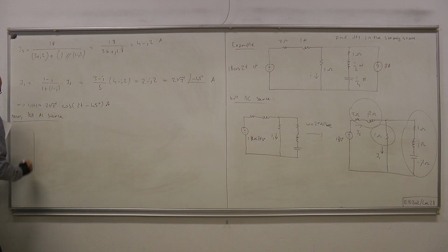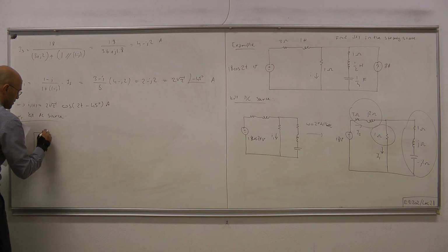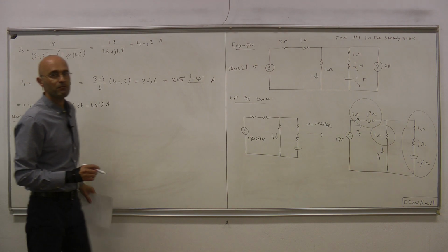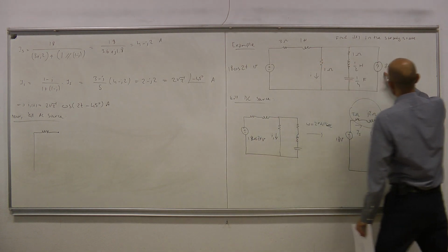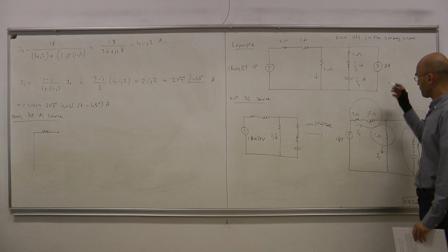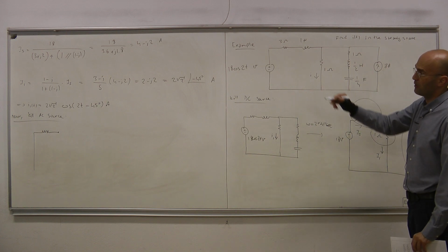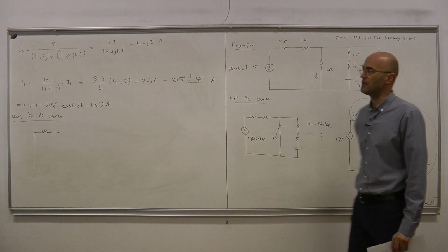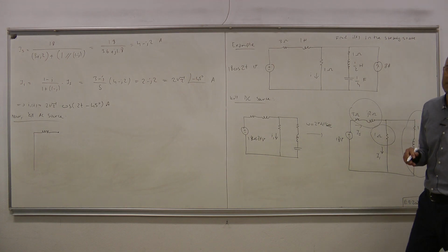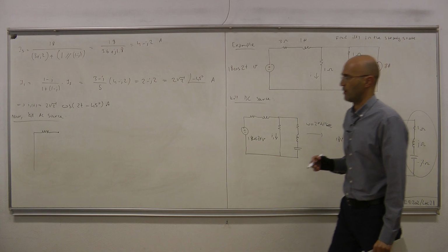That voltage source is replaced by a short circuit, and then we have 3 ohm. How about the inductor? Now we know that this is the DC source, and we're talking about steady state, therefore the DC steady state, because the only source that's active in that circuit is the DC source. And we know that in DC steady state, inductors behave like short circuits.